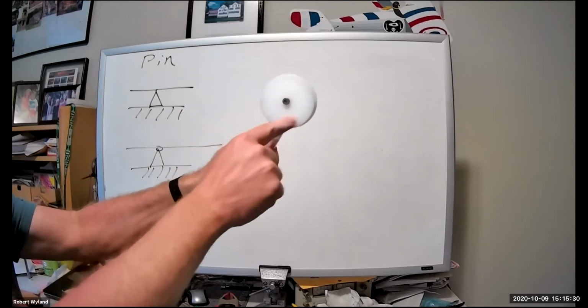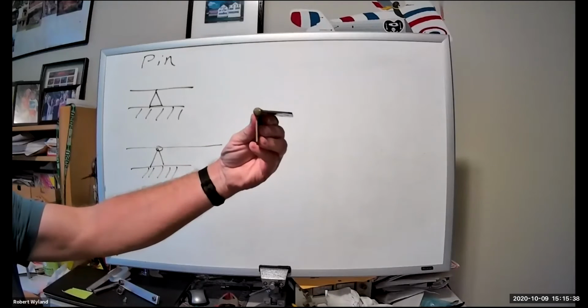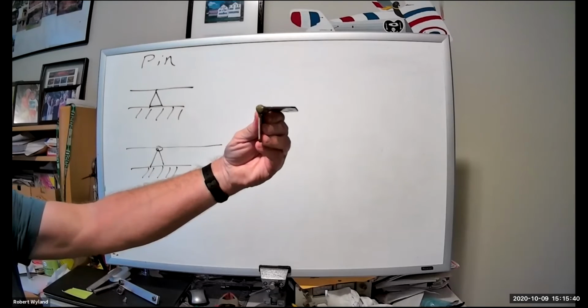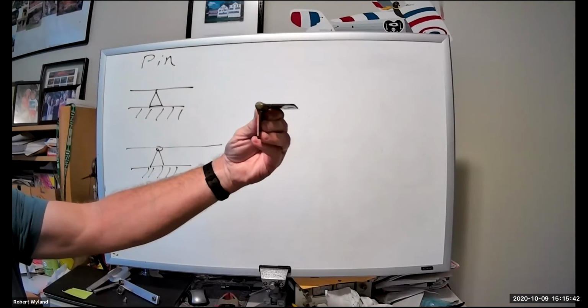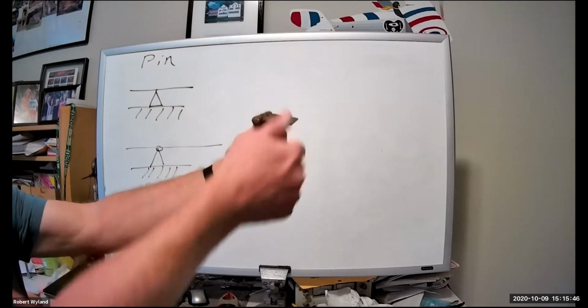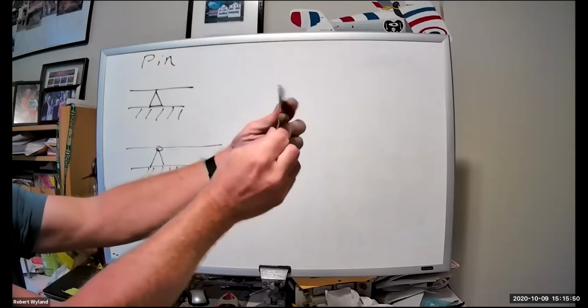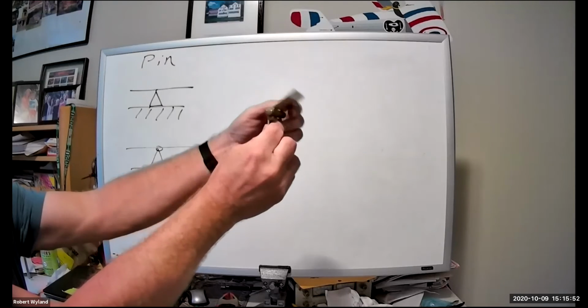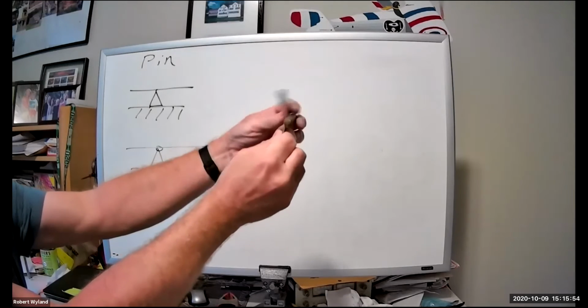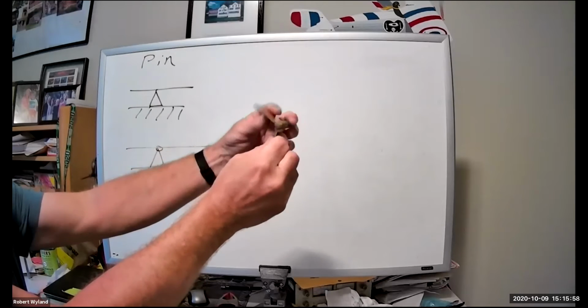All right. And so what we're going to try and establish is how the forces in 2 dimensions, what forces can possibly react with this. So if I'm looking at moments and I try and create a moment, clearly I'm able to swing this piece back and forth. And so there's no moment resisting. So there's no reaction in the moment. There's no moment in the reaction.